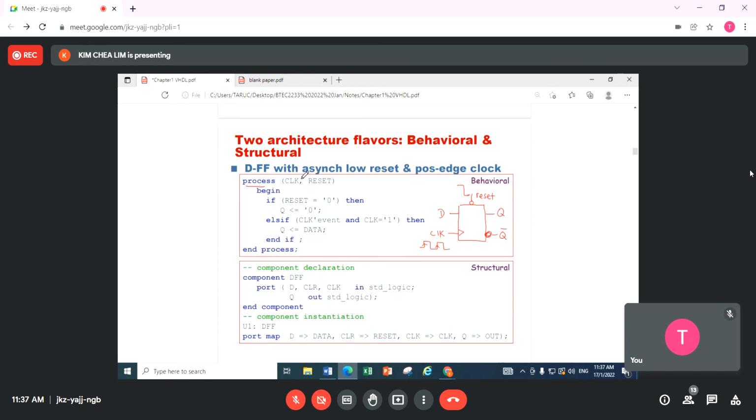If no changes happen at these two, let's say the clock is spoilt already and reset is forever at logic 1, then you find that they won't need to work. They can sleep. That is the purpose of the process sensitivity list. For all flip-flops, if you want them to work, responding to clock, reset, or even preset, you must put whatever they are sensitive to into this list here. It can have more than one, 3 or 4.